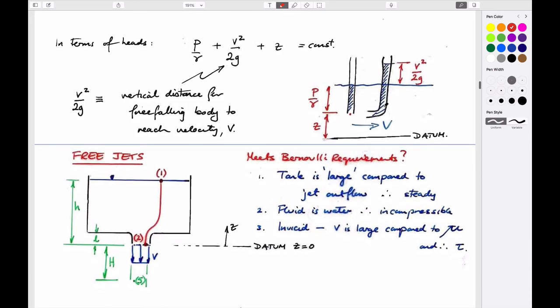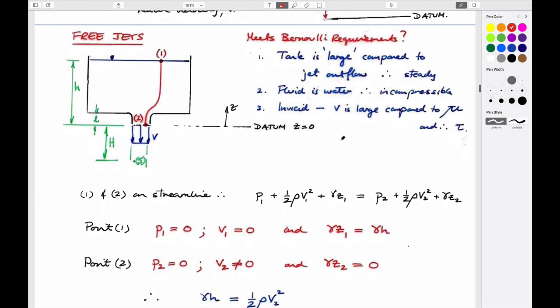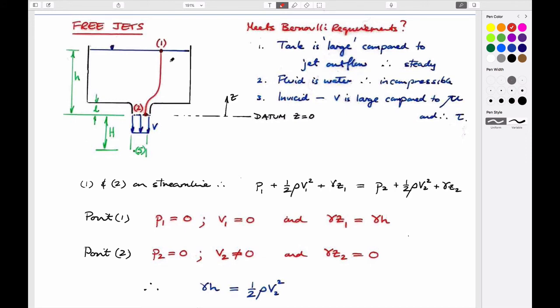We talked about measuring pressures with pitot tubes, and the fact that in some manometer equations, if the velocity goes to zero, you'll build a dynamic pressure as a function of that, and the magnitude of that you can calculate by writing Bernoulli between an upstream and a downstream location, and we know how to do that. We talked about equations for free jets, which is just the straightforward application of Bernoulli's equation between an upstream location and a downstream location. We just have to be careful to be able to define the appropriate boundary conditions.